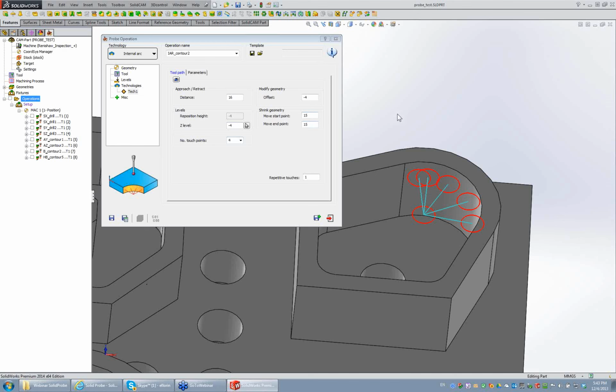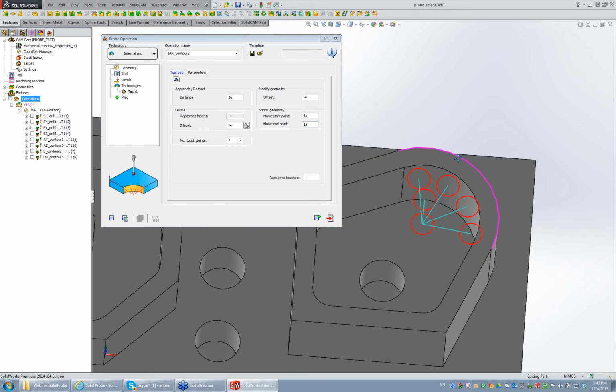What is a cycle? It's a macro program in the controller. If you know the macro language, you can write for yourself a cycle with 5 or 6 measurement points if you want more precision. Just tell us the number of the cycle and we will output the special cycle that you wrote.